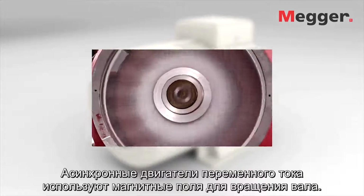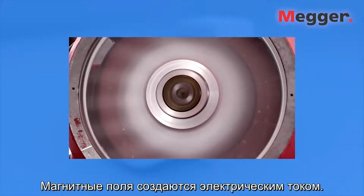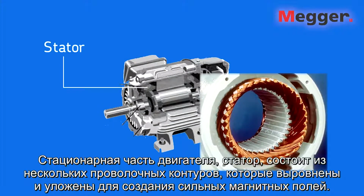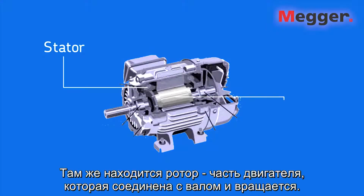Industrial AC induction motors use magnetic fields to cause the shaft rotation. Magnetic fields are created by electric currents. The AC power source provides the currents that flow in the motor. The stationary part of the motor, the stator, is made of several wire loops, which are physically aligned to create strong magnetic fields. Due to the AC nature of the power source, the magnetic field direction rotates in the center of the stator. In the center of the stator is the rotor, the part of the motor which is connected to the shaft and rotates.